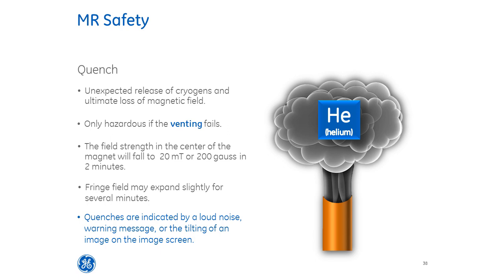For example, let's say that there was construction done to the building and the stack was rerouted, adding several turns and bends to the path. The helium from the quench expands very rapidly and needs to have a clear path to the outside. So the ownership of the vent stack goes to the customer.